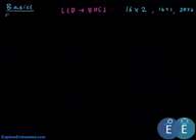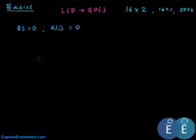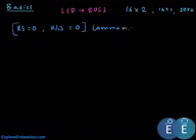For all the commands, as you could guess, the register select line should be 0, and since we will be writing all the commands into the graphics controller, read/write bar would be 0 for all the commands that we discuss now.